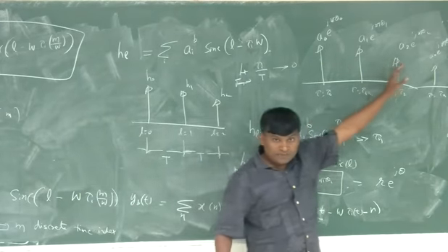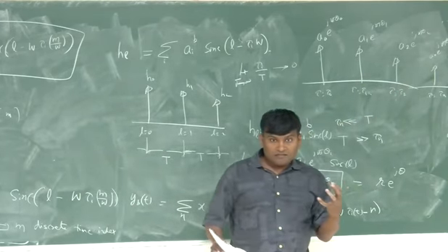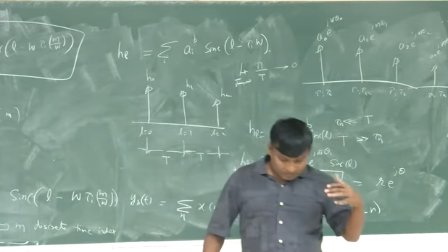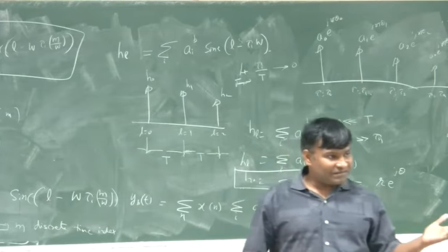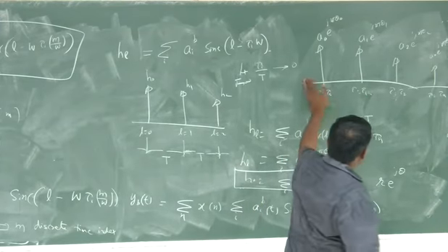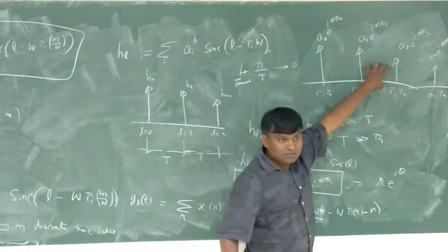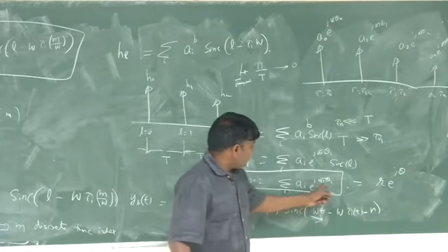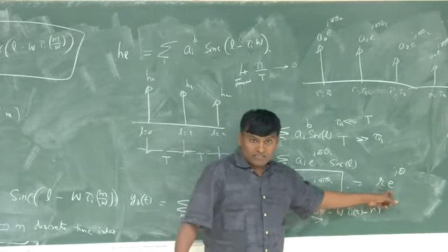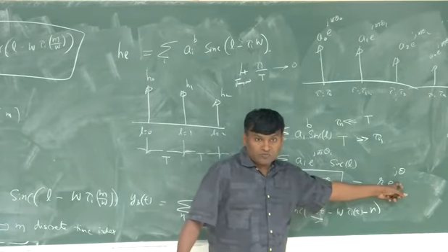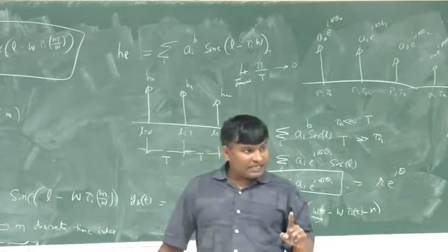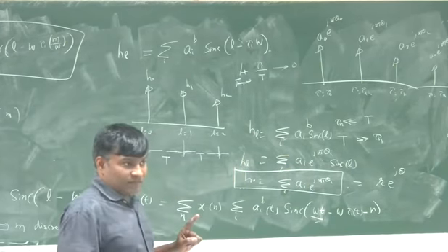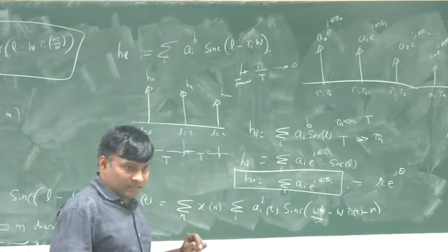We have a lot of taps, and they are all very close to each other compared to the signaling interval. Capital T is very large compared to these taps. All these taps will merge into a single effective tap, and the envelope will have a Rayleigh distribution. Theta will have a uniform distribution. We call it a flat fading channel, or narrow band flat fading channel.